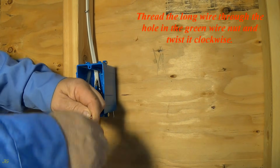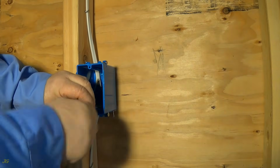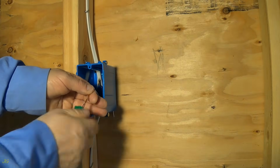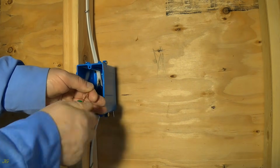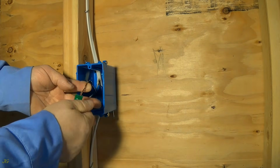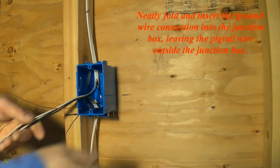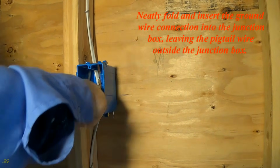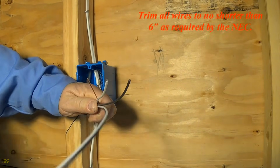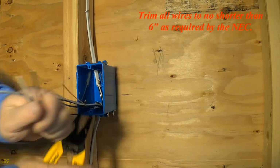Thread the long wire through the hole in the green wire nut and twist it clockwise. Neatly fold and insert the ground wire connection into the junction box, leaving the pigtail wire outside the junction box. Trim all wires to no shorter than 6 inches as required by the NEC.